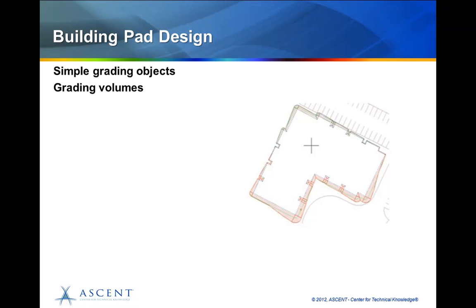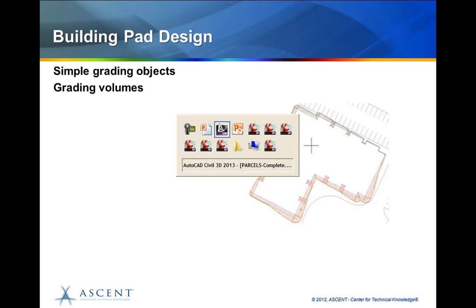Now with the building pad design, for those of you that have taken the fundamentals class for 2013, you'll know that there is a grading exercise in there, and it's a very simple grading exercise. The building pad design is very similar to that exercise. We start out with a feature line of the building and then grade out to the surface, and then we go in and we use grading volume tools to balance the site. So let's take a look at that in the software.